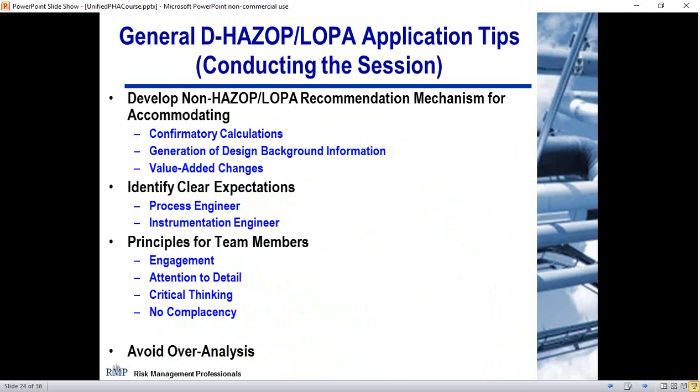What I also would encourage is updating master copies of the drawings. If you see little problems, just fix them. Things like missing tag numbers, drawing corrections, piping specs, a lot of things that are just obvious as part of best practice, or just oops, things that were missed during the design. Just fix them on the spot and move on, and then the copies of the master drawings can be included as an appendix for the HAZOP study, so there's a clear continuity of the record.